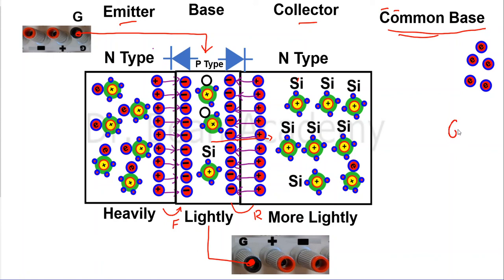To make a PN junction forward biased, we need to connect N type with the negative and P type with the positive terminal. The base is a P-type semiconductor, because I am considering only an npn transistor, so the only way I can make this junction forward biased is to connect the N-type emitter with the negative terminal, because only negative is at a lower potential than ground.